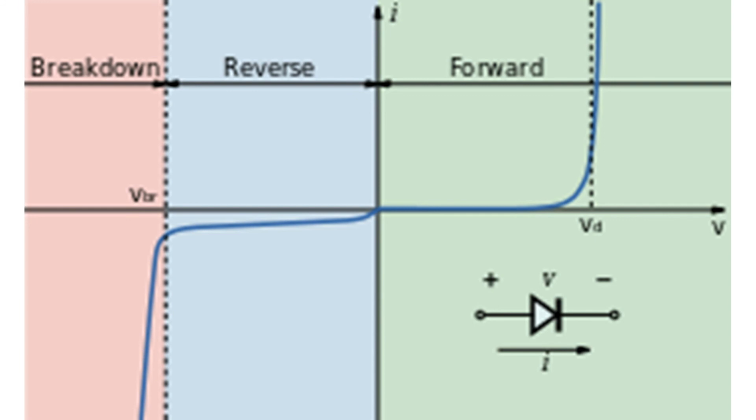Here's a graph of the diode in forward bias and reverse bias. As you can see here, you can instantly tell that once you get to 0.7 volts, current will start to flow through the diode if it's forward bias.